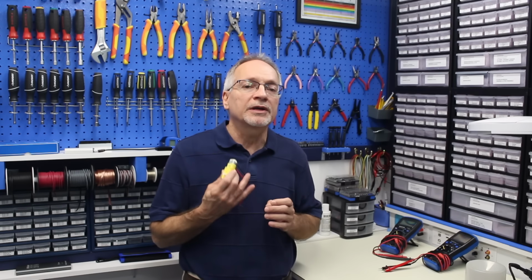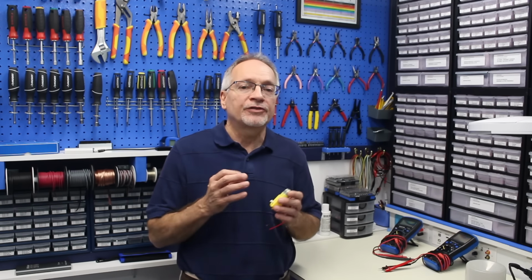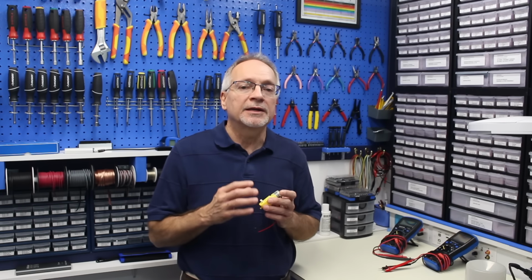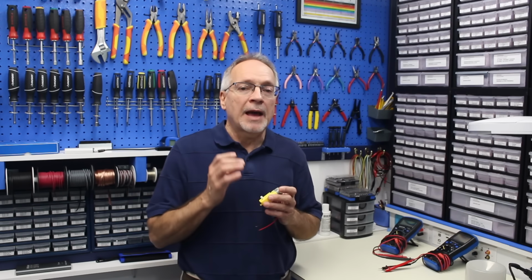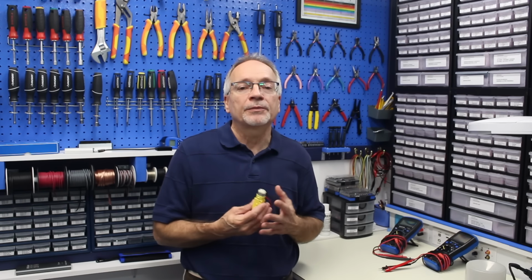Now, the difference with a motor and a solenoid and some other devices is they are inductive loads. They have a coil inside them, or several coils inside them. And what happens when you power an inductive load up is that a reverse or back EMF is created. This is a voltage of the opposite polarity. And when you first apply power, this voltage appears on the circuit very briefly. However, it is there long enough to potentially destroy your transistor. And so you need to do something about that.